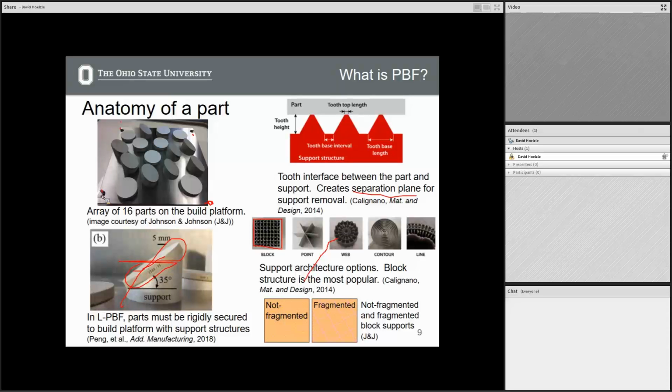But we build these on really, really large pieces of metal, and that's if we want a heat sink. Heat sinks are more effective when they're really large in terms of trying to keep this build platform relatively cool. So basically most of the heat is going to be going into the build substrate as a gigantic heat sink.